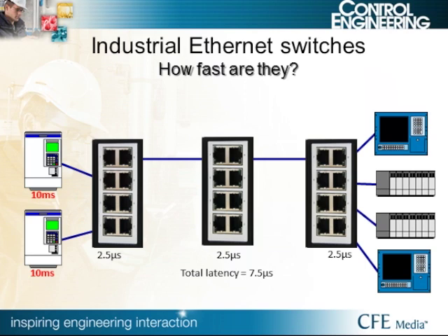As our networks get larger, how much effect does it have to add switches between our devices? Industrial Ethernet switches built within the last 5 years have a latency of about 2.5 microseconds. Typical control networks usually will go as low as 10 millisecond updates with the drive, servos, or I/O.